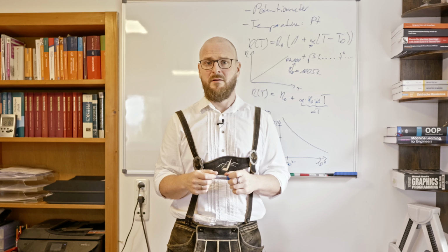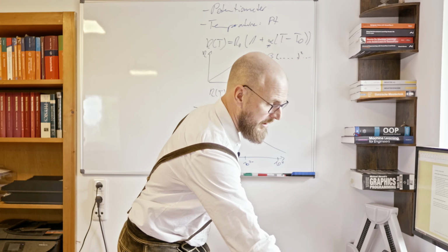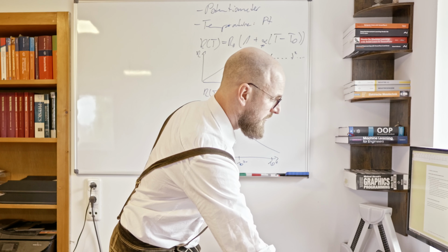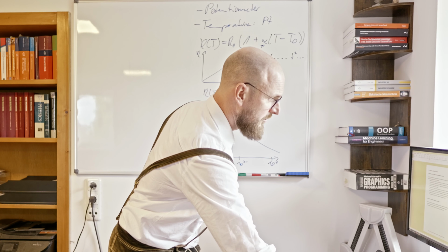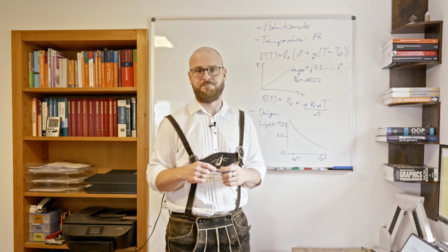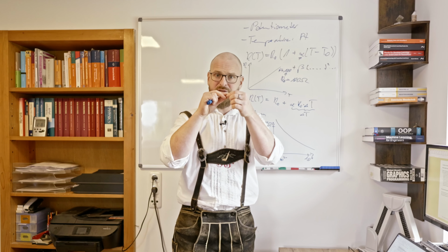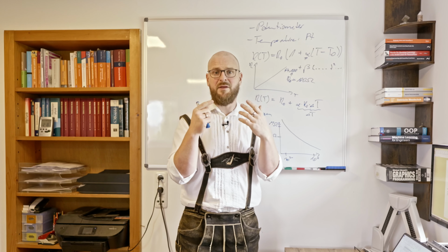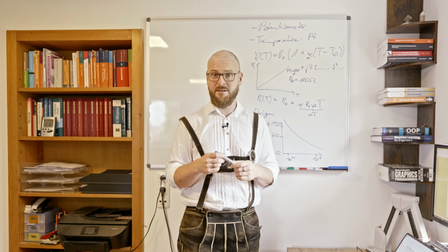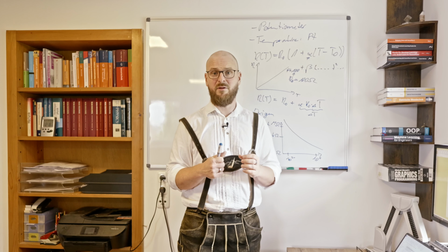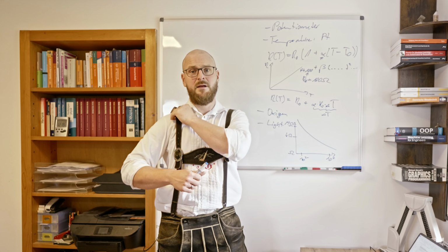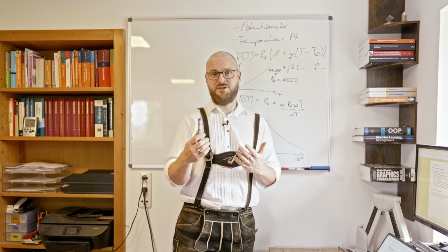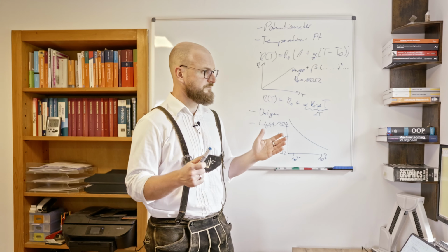That's used, for example, in another type of measuring equipment, which is called strain gauges. Strain gauges simply use the fact that we have a resistor which is stretched or compressed, and by that changes its resistance, and that can be measured. That's very usable for small distances, and on the other hand, for very fast distance changes, for vibrations, for example.